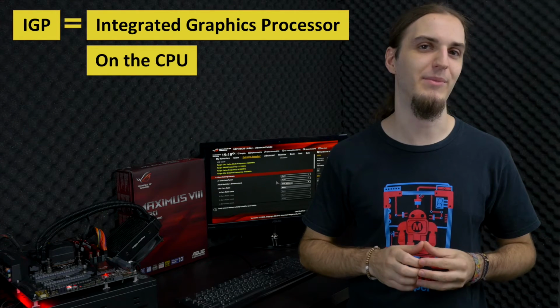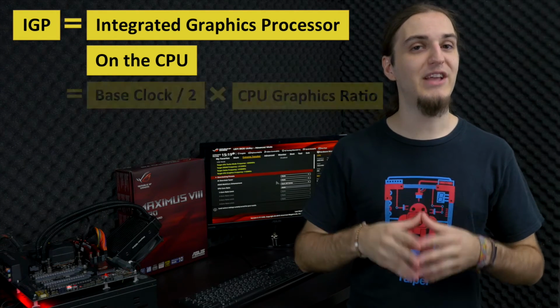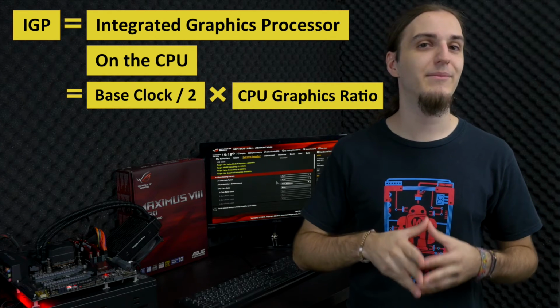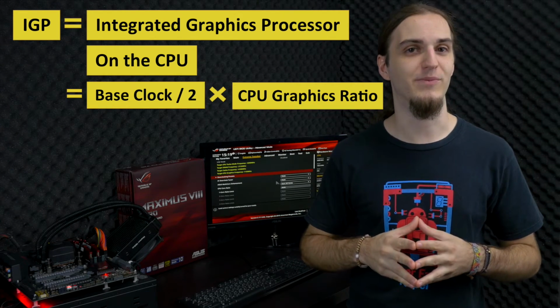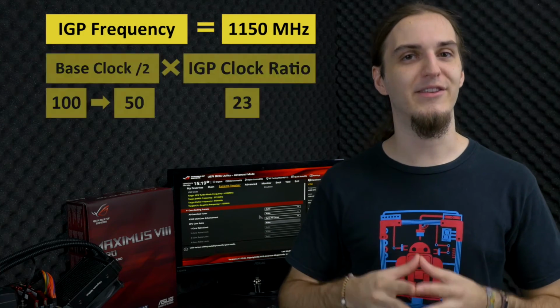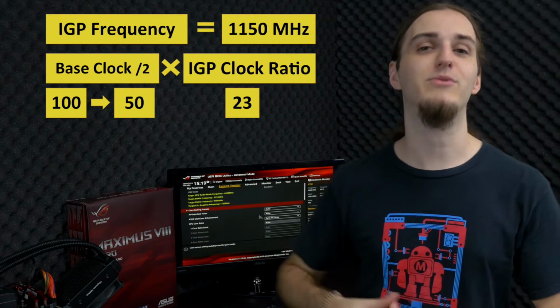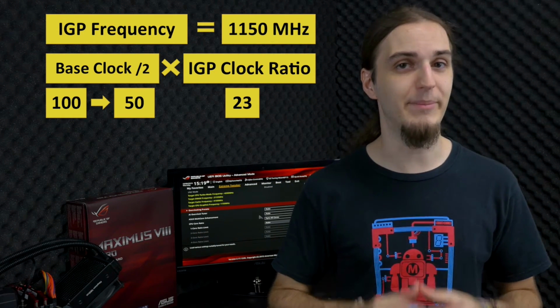As a last step, we will be overclocking the IGP. The IGP is the integrated graphics on the CPU. For Skylake, the IGP frequency equals half of the base clock frequency times the CPU graphics ratio. Remember, with the default base clock set at 100 MHz, and the CPU graphics ratio set at 23, our default IGP here is running at 1150 MHz.